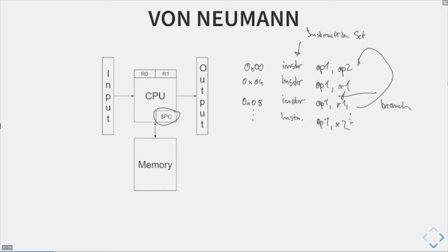Now, one thing that I asked you beforehand is what's the difference between an 8, 16, 32-bit, 64-bit CPU. One difference is the bit width of this connection between the CPU and the memory. If we talk about a 32-bit CPU, it usually means 32-bit wide memory accesses that you can execute in one clock cycle via this memory bus.